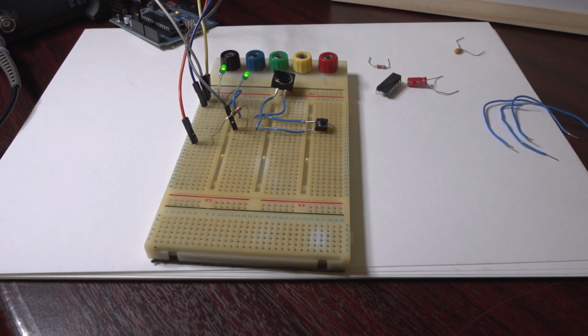Okay, so that concludes the video. We've looked at a hardware solution to debounce the switch, to get a reliable single activation every time you press the switch without contact bounce. Done that in hardware using an RC filter and a Schmitt trigger on the output of that. We've looked at how to calculate the values for the amount of time that you want. And we've also looked at a software solution which basically does a very similar job, probably good enough in a lot of applications, and it doesn't require those extra components. There's two solutions here. You can go for a hardware solution or you can go for a software solution, and they both pretty much allow you to debounce the switch and get good reliable presses.